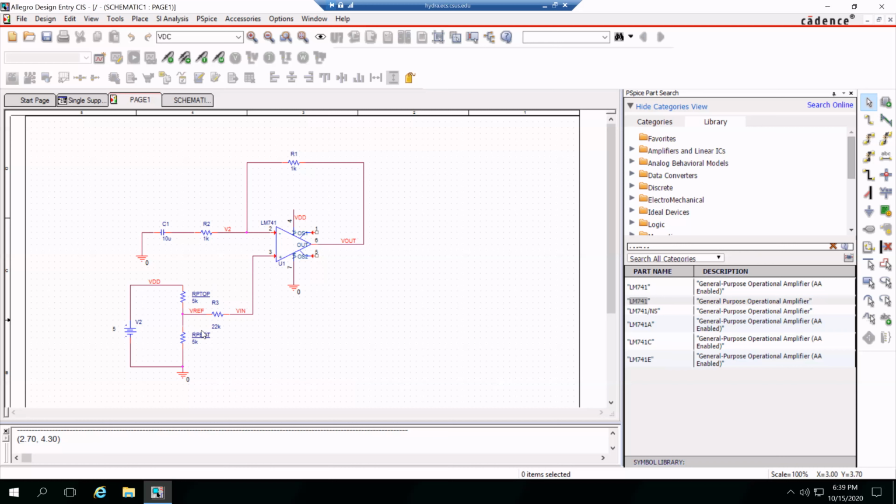All right, so let's talk about the extreme conditions now. What if your wiper is all the way up at VDD? Well, now RP top is 0. So you have 0 in parallel with 5K. Well, what's 0? You know, parallel resistance, fundamental rule of thumb, it's always going to be the lowest value, right? Or less. So if it's 0, 0 times anything is 0. So at VDD, it's just 22K plus 0.